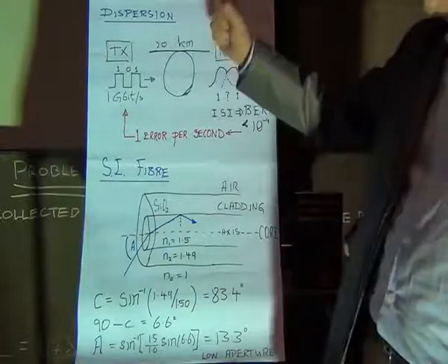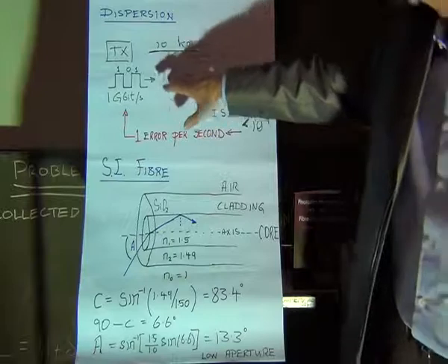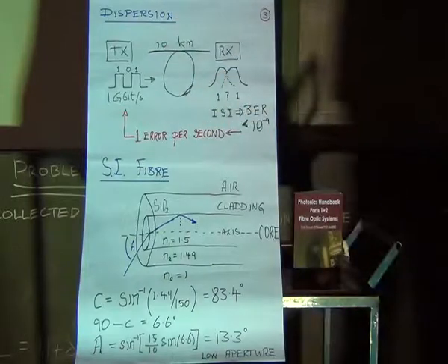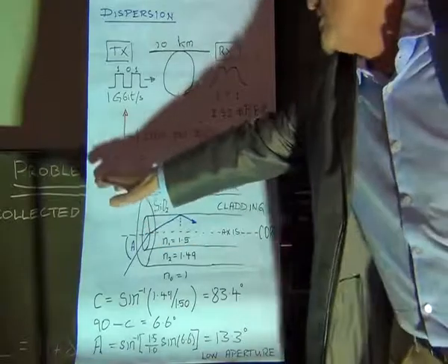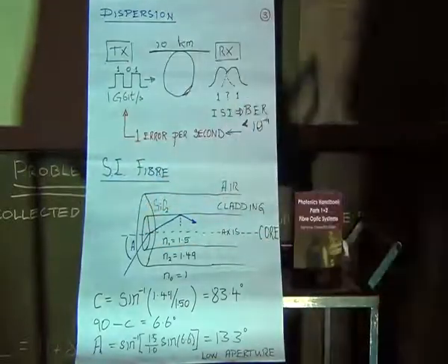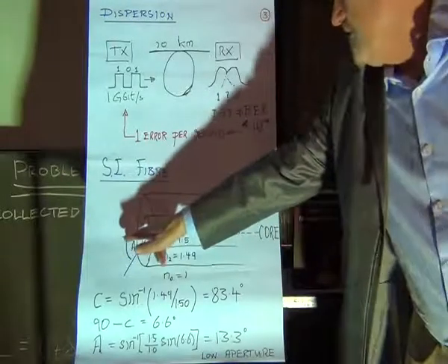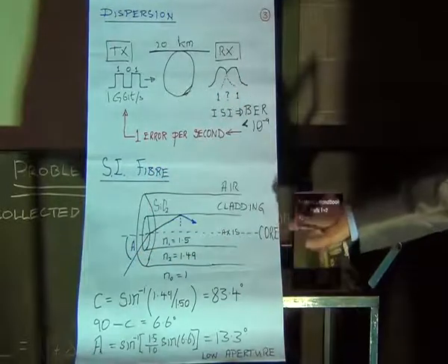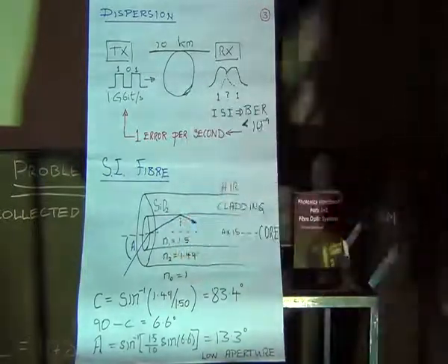Right, I talked then about the profile of the index in the fibre mimicking the original preform. Typically, we would use a step index fibre of a design something like this. Here we have the axis of the cylinder, that's the optical fibre, and the refractive index of glass 1.5.